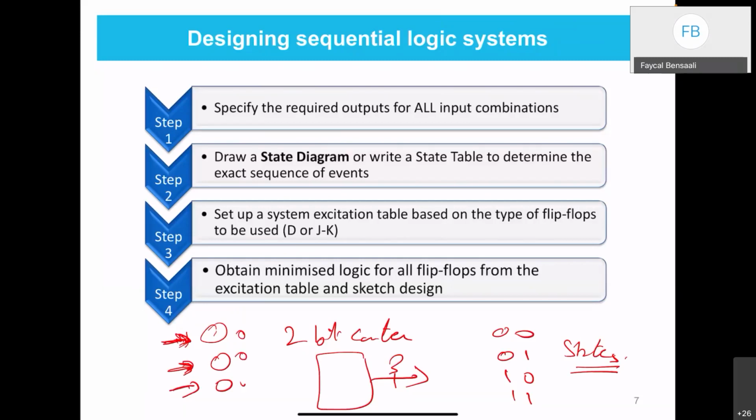So when do you need 0 0 0? When do you need 0 1 0? When do you need 1 1 0? And you may not have all the states, like in a counter, or the opposite. You can have just 2 states or 3 states. Even with 3 bits, you may have just those valid states in your circuit, and you don't need the other states. So your circuit will have 3 states and you will need 3 bits. It doesn't mean that if you have 3 bits, you will need to use all possible cases. No. For a counter, yes, we use all possible cases.